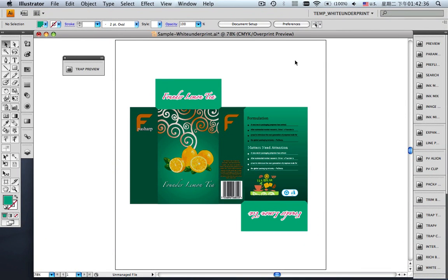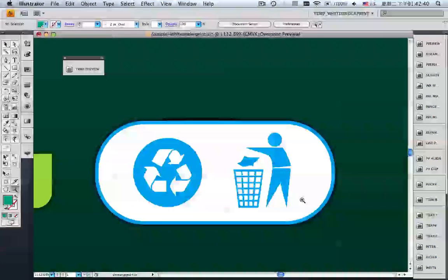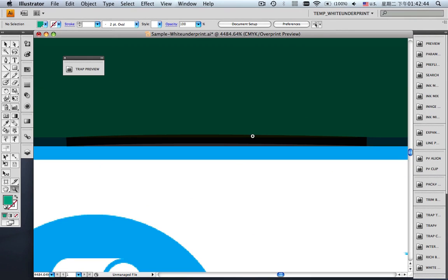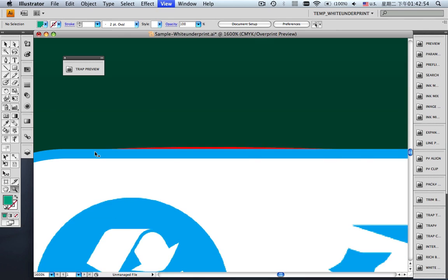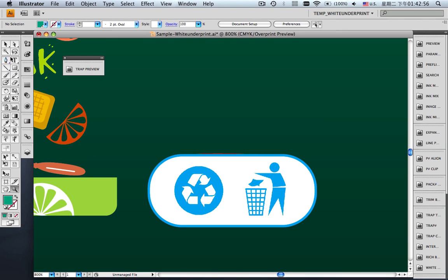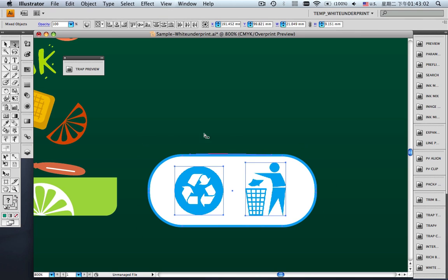You can see that there is a small red gap in the right bottom image. In maximum gap mode, if the distance between the two objects is smaller than the preset value, then the gap will be filled automatically. This is much more helpful for the operators because such kind of gaps may destroy the whole packaging, because sometimes it's kind of invisible to human eyes.